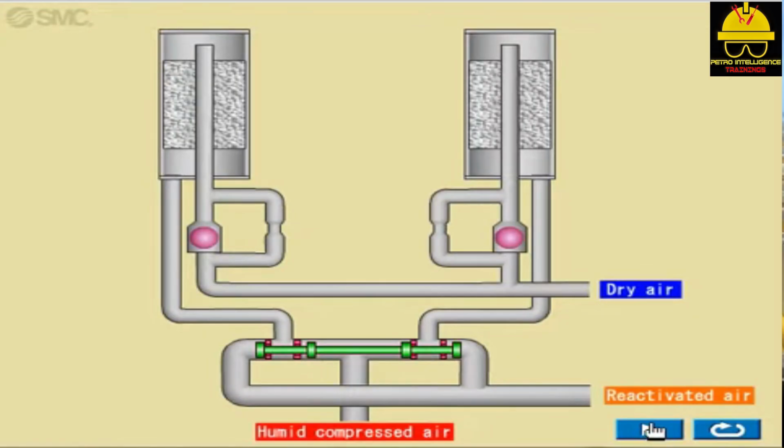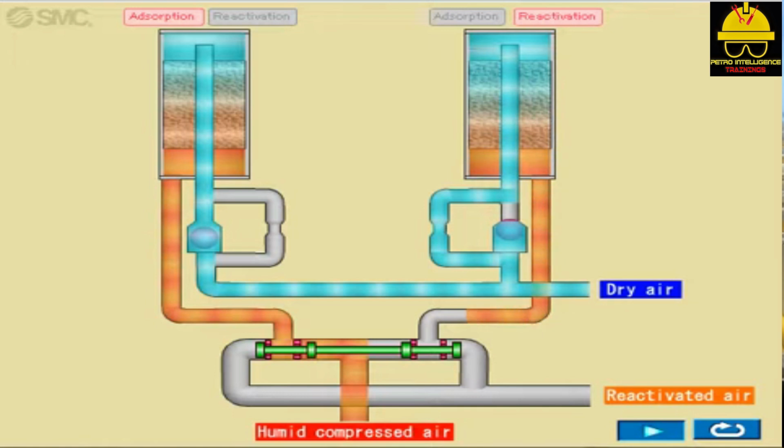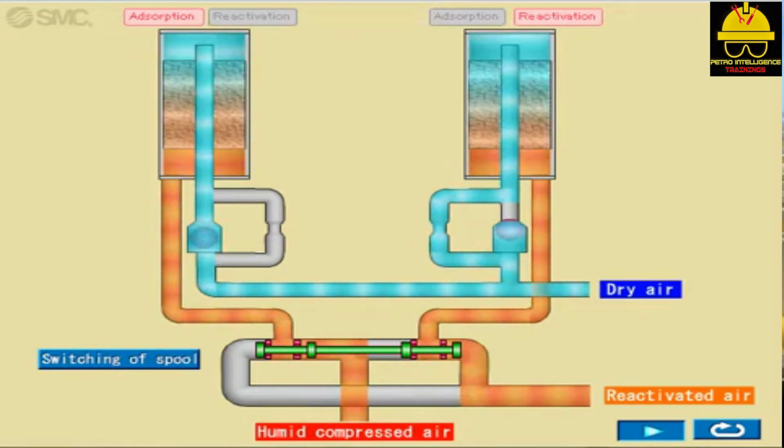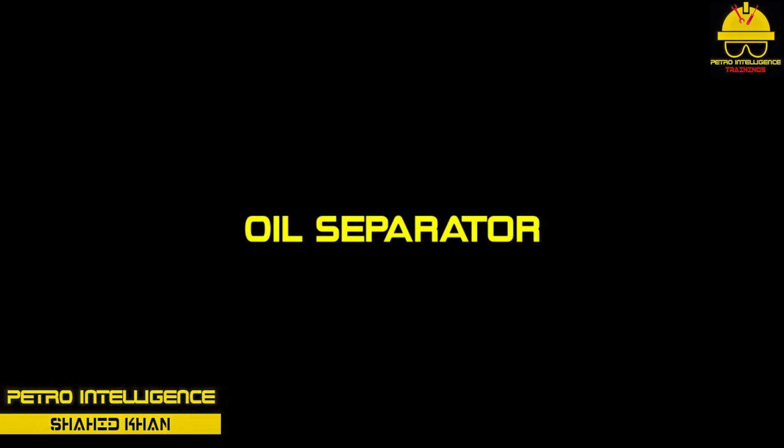Dry air. For extremely dry air service, the discharge of a compressor is run through a dryer. Dryers filled with moisture-absorbing chemicals are called desiccant dryers. Alumina, molecular sieves, and silica gel are the most common types of chemicals used in dryers. Typical dryer operation uses parallel or series dryers. Both arrangements allow one dryer to be in service while the other is being regenerated. The regeneration process uses dry, clean, heated gas to strip the moisture out of the spent dryer.